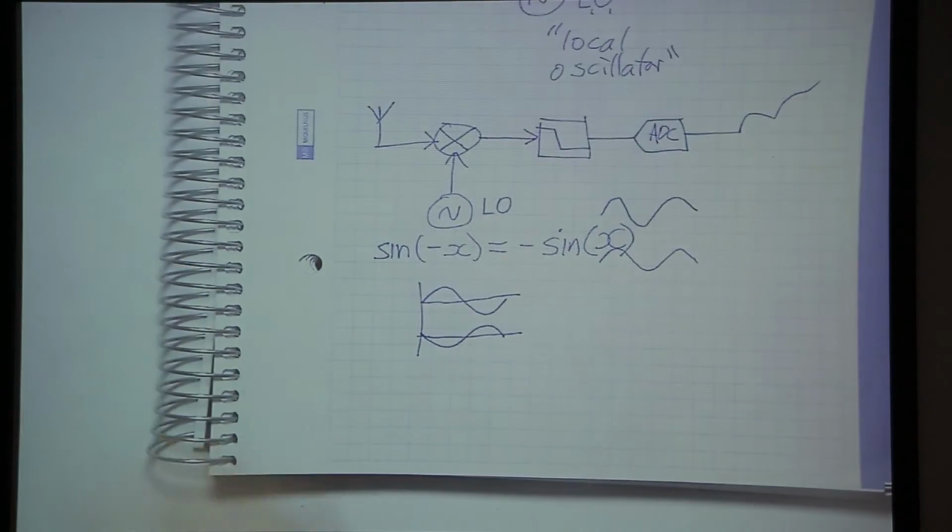So the idea here is that if we could somehow work out the phase of a signal that we receive from a mixer, in addition to its current amplitude and frequency, we'd be able to tell whether it was originally at a positive or negative frequency. And that's really important for being able to do most digital signal processing with a result. There are ways around it beyond the normal technique, but...